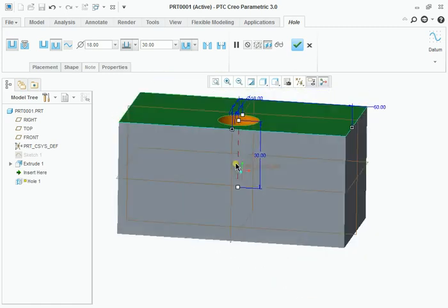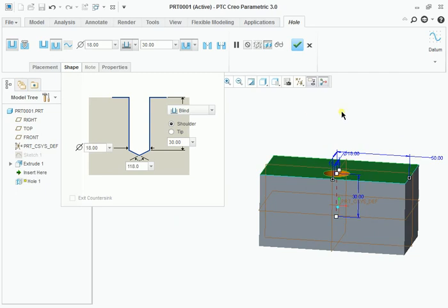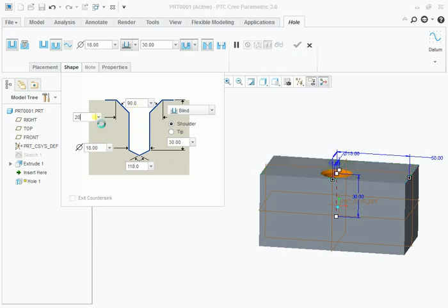You can also see the shape of a hole under the shapes, and these are all the options to specify the countersink and counterbore commands. You can see the nomenclature of the hole, the diameter of the hole body, the countersink feature, the countersink angle, and the depth commands. The depth is measured in two methods: from the reference to the shoulder, and up to the tip.